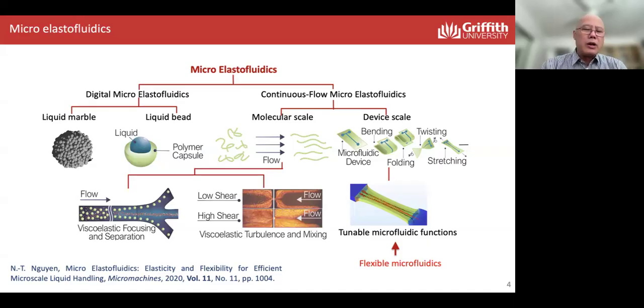And at low Reynolds number, normally you won't expect to have turbulent flow because friction force is much higher than inertial force. So we forget about inertial forces, but with the coiling and recoiling of small molecules, you can have so-called elastic turbulence, which can have local turbulence effects, and that leads to a number of applications as well. You can use it for separation, mixing, and so on.